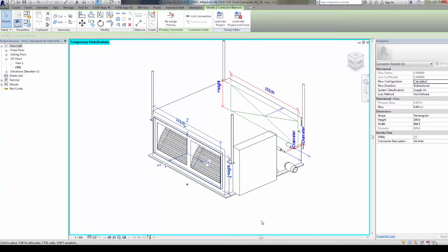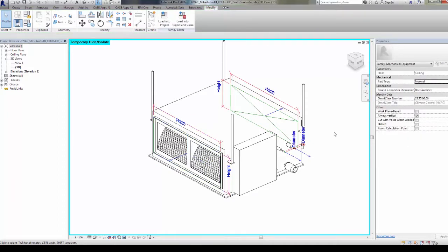As an example, we are directly changing the direction of the connector, and it may be possible to resize it as well. We see that it has neither parameters nor dimensions associated. Then, it will be possible to link it to some parameters in order to have a parameterized model. As well, if the system classification had not been correctly associated, it could be necessary to assign it the right one. Nevertheless, in the current example we are adjusting the plenum instead of the indoor unit, since in order to explain the necessary adjustment for each manufacturer, each of them should provide their own instructions in order to handle their families.